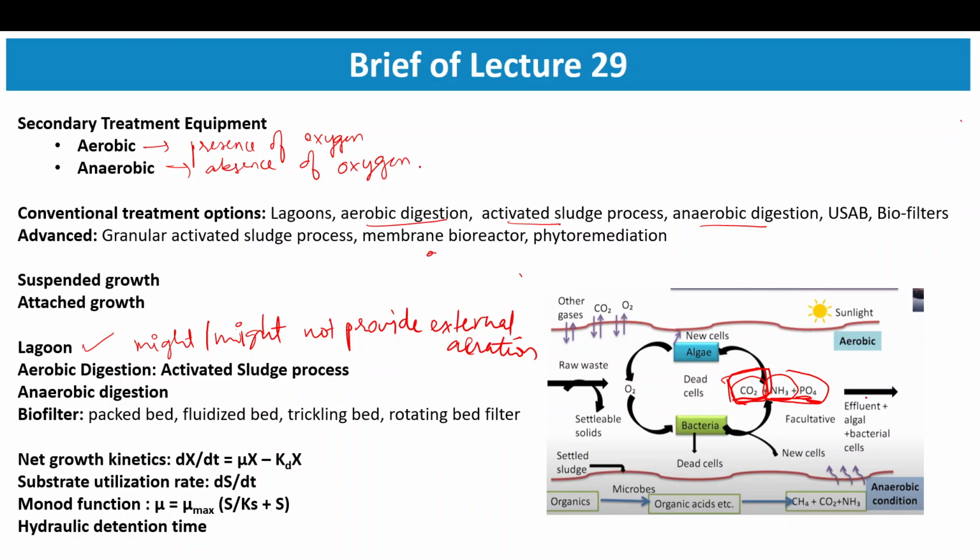But as we go deeper into the pond or lagoon, at the lower portions there are chances that sludge is deposited, and the oxygen concentration also reduces. If there is any organic left in this sludge, we can provide microbes here which are specific for anaerobic digestion, so they degrade the organics to form CH4 through anaerobic digestion.